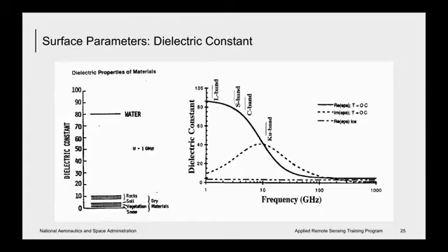So for example, for dry, naturally occurring materials, their dielectric is on the range of 3 to 8. For liquid water, it is around 40 to 80, so it's frequency dependent. And therefore, the amount of moisture in the soil or vegetation can greatly influence an increase in radar reflectivity. Generally, reflectivity and image brightness increases with increased moisture content, which means that there is also less penetration through the medium.